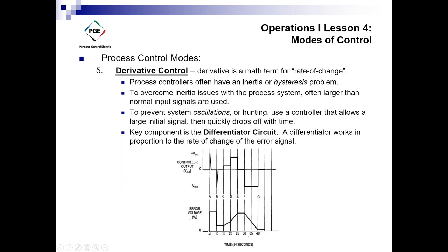So here you've got the error signal. You get a large spike in the voltage. You can see the controller, this is just straight derivative, peaks, overcomes the inertia of the system, gets it moving, and then it comes back down here. And now you've got some steady state new level, and then you can see right here, steady state new level here, not here.